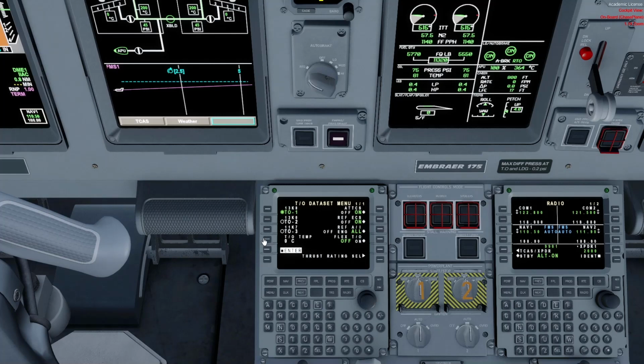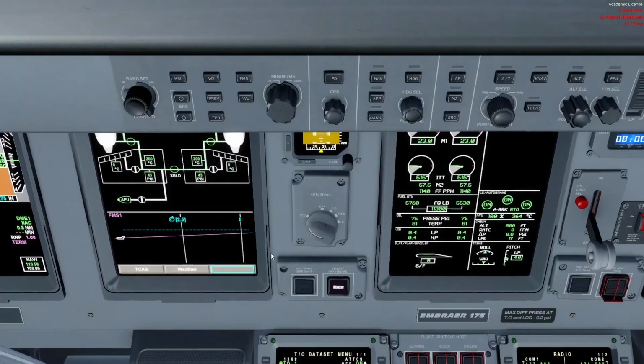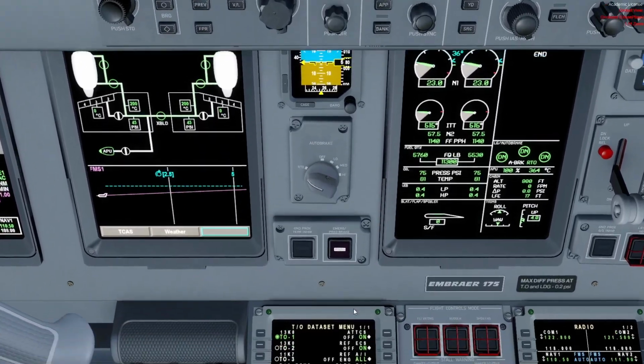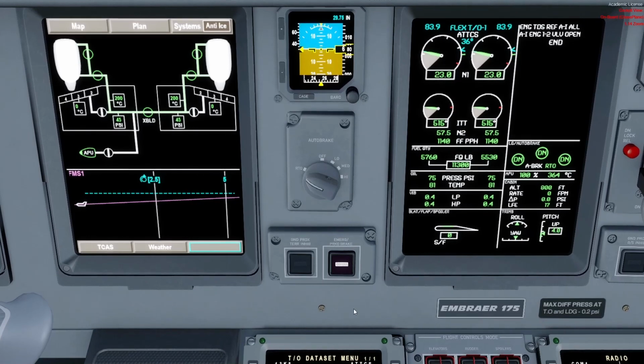So I'll just finish setting it up here. Takeoff temperature, we said 3 degrees. And the runway is not contaminated, just wet, and we can use flex temperature, let's say to 36 degrees. And it would obviously all be calculated meticulously, but for argument's sake, let's say this is what comes out. So right after I did that and hit enter, look now what happened.